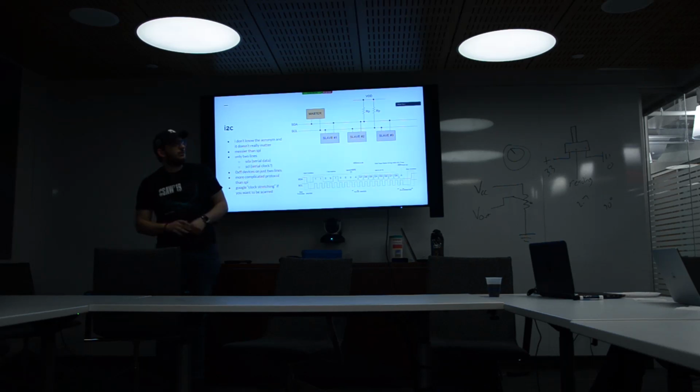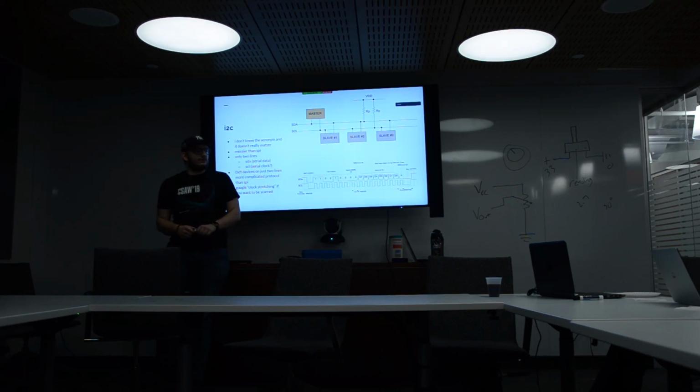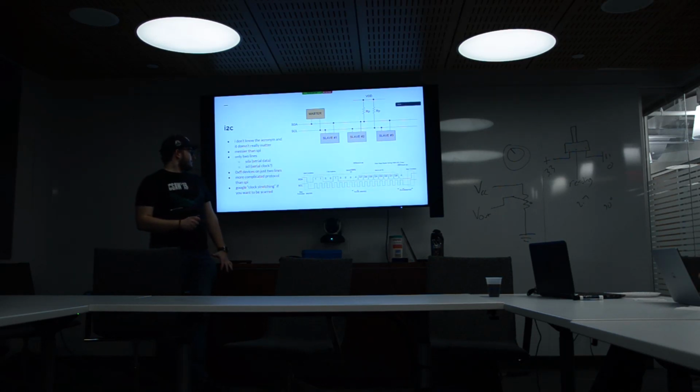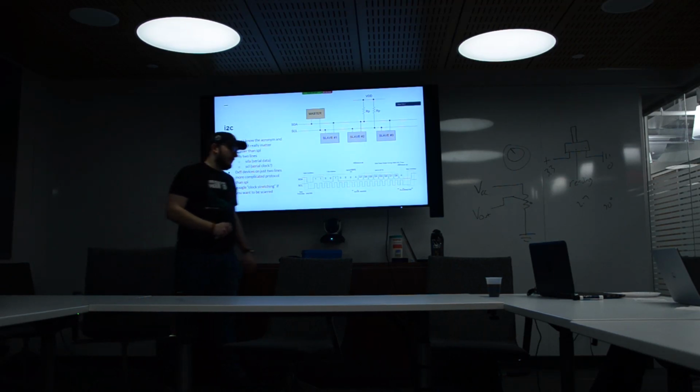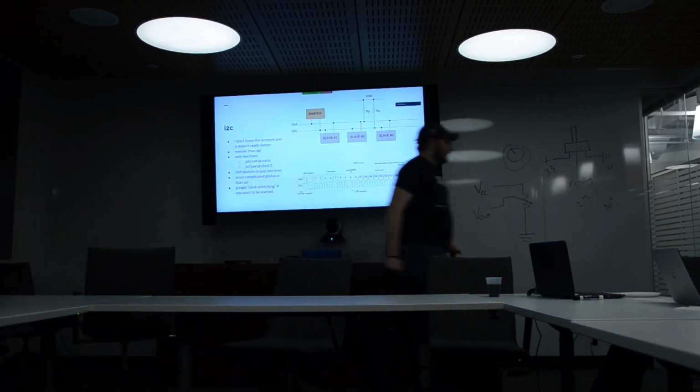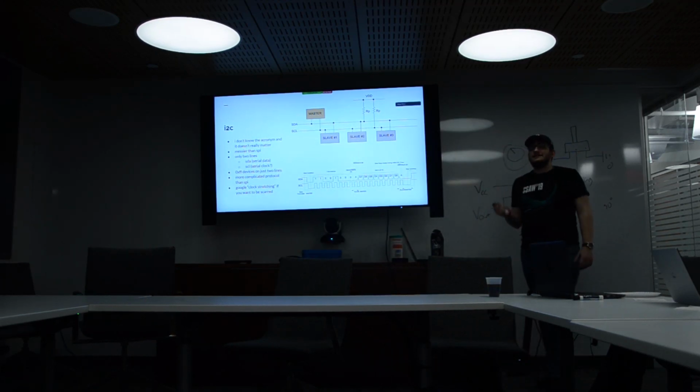So that makes I2C more of a network-like protocol, which is more familiar to the people in this room, I would say, than SPI, which is purely just hardware. If you can see it, you can listen to it. Yeah, it's really complicated and bad. Clock stretching is a thing, and it's basically just a way of one device telling another device, wait, I'm not done. And it's a really complicated, awful protocol, but I'm teaching about it because it's important because it gets used a lot. And it gets used a lot because it's cheap to implement.